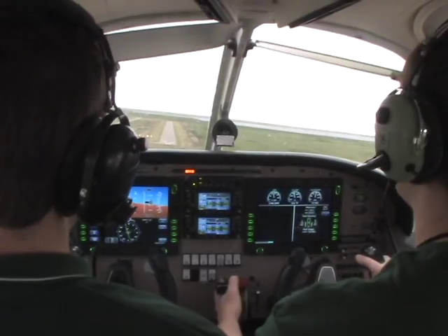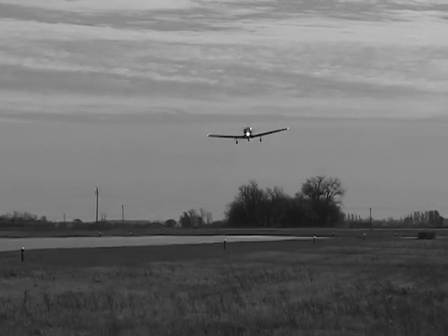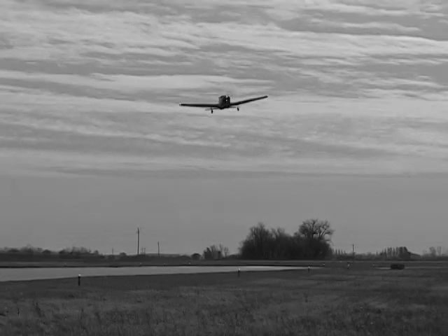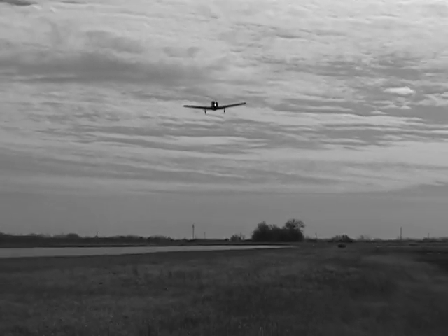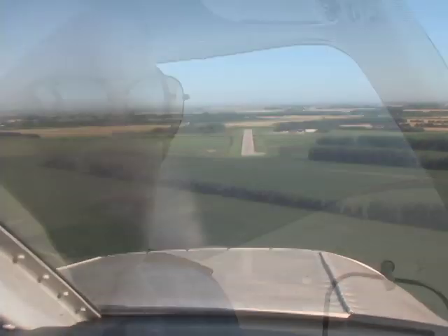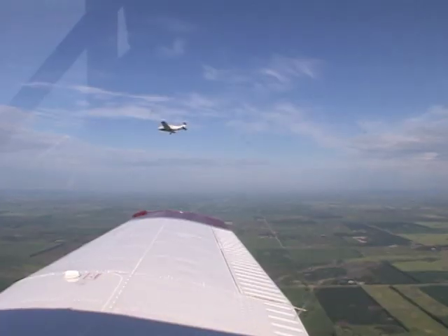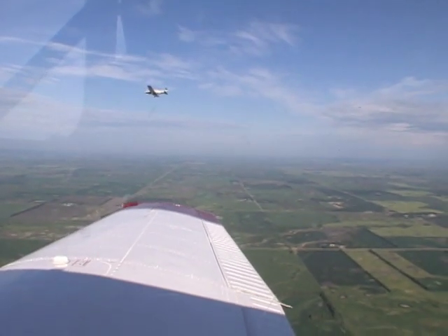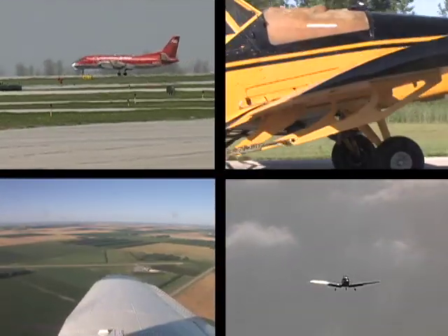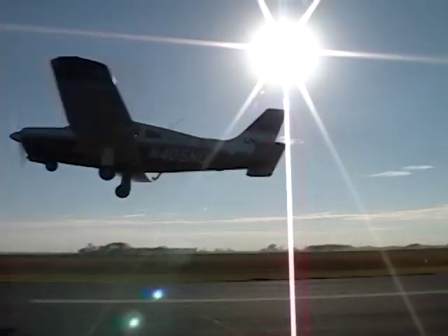The PIC must follow all ATC clearances. If unable to comply with a clearance, however, it is once again the responsibility of the PIC to advise ATC immediately that they are unable to comply. And it's a whole different ballgame at non-towered airports. The pilot must be situationally aware to the point that they can communicate directly with other traffic and maintain adequate separation at all times. You can think of non-towered operations as all pilots working together to achieve a common goal, which is getting safely on the ground or safely in the air.